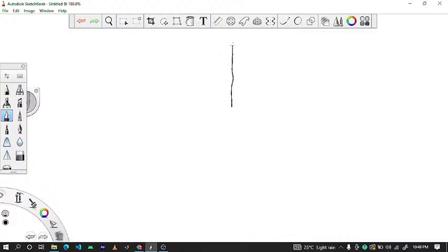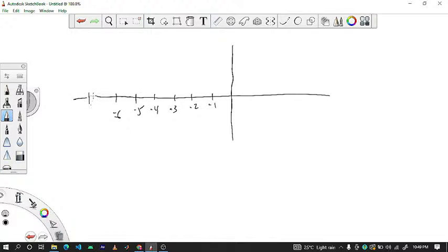We can draw. So let's see, let's make a very nice sketch here. Minus 1, minus 2, minus 3, minus 4, minus 5, minus 6, minus 7, minus 8. We said that minus 1 was a pole, minus 2 was a 0, minus 6 was a pole, minus 8 was a pole. We said this is element number 1, so there will be a locus to its left. Element number 3, there will be a locus to its left too. So I have it like this.